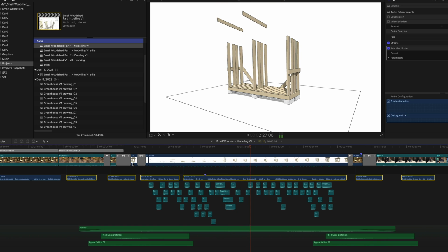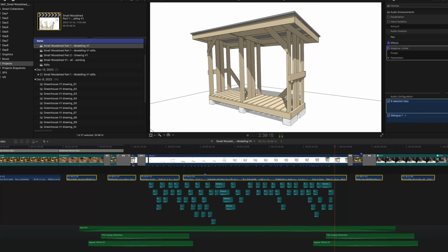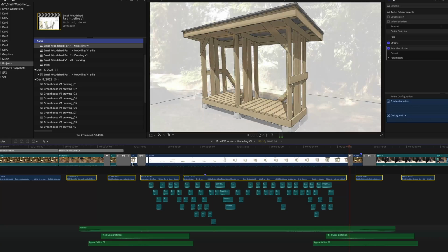Then 2 floor braces around the back and 4 rafters with blocking. Connecting the walls and rafters are 4 1x6s and front corner braces. Fascia boards complete the overhangs, and the shed is topped with strapping boards and a metal roof.